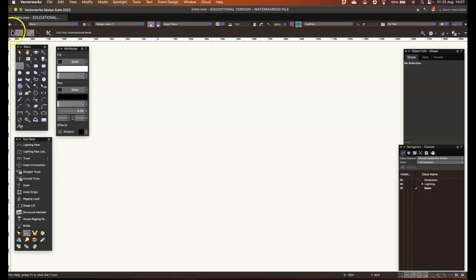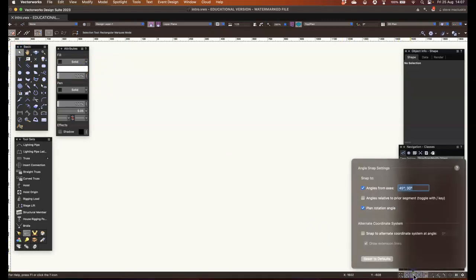The line has a constrained mode, which limits them to angles of 90 degrees and as defined in the smart cursor settings. So that means that the lines are 90 degrees, 60, 45, 30 and back to 0 again. We can define anything we want in the smart cursor settings. There's snap to angle there. If we double click that and open up, we've got 45, 30.